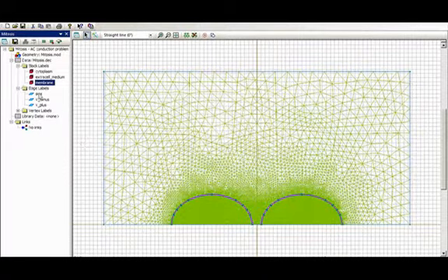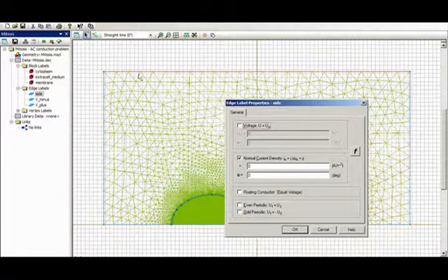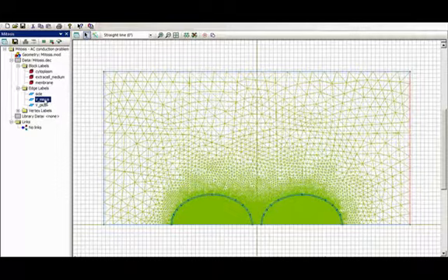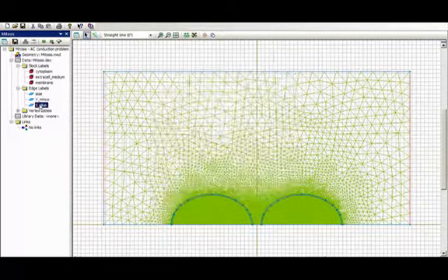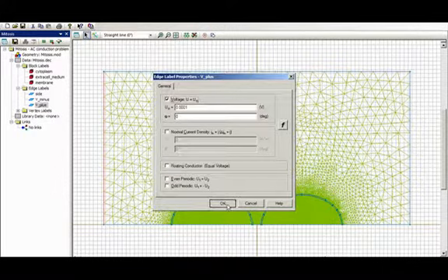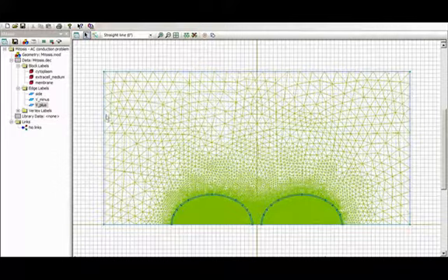They're lipid bilayers. Now this is the edge of the solution region, so you can think of this as like a cylinder. It's rotated about here. And I've assigned a 0 normal current density to the edge of the cylinder. Okay. Now on each side of the model, I've assigned opposite potentials, roughly negative 0.1 millivolts to the right and 0.1 millivolts to the left. You might be able to see that this problem has an additional symmetry because these are opposite potentials. The central boundary will be an equipotential of 0 volts. So I could just as accurately model this problem by discarding half of it and assigning a 0 voltage boundary condition directly in between. However, it doesn't take very long to solve the problem, and we'll just leave it here for visual effect.